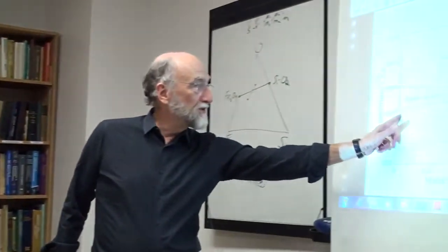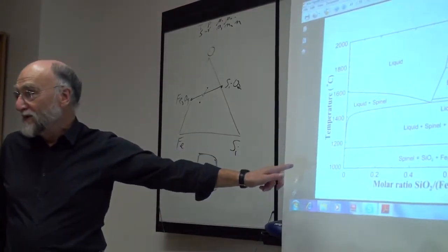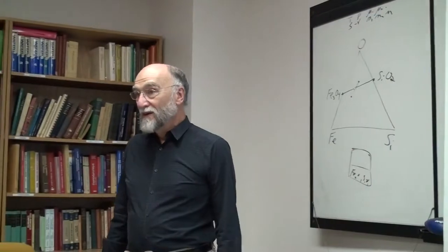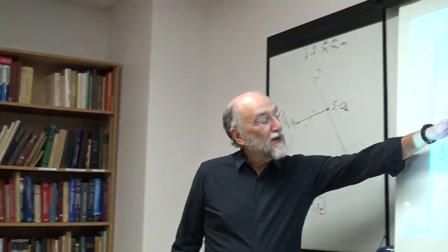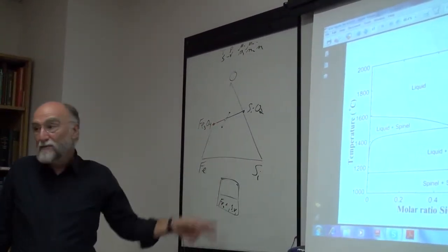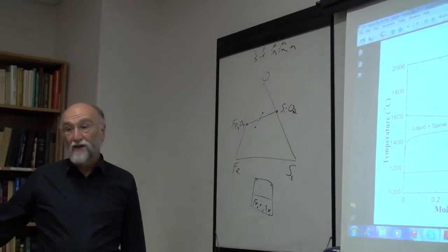You can see, for example, this is not what a binary phase diagram looks like. This is simply an isoplethal section across the system. In other systems you might find that it's fairly close to quasi-binary: most of the tie lines lie pretty close to that line, but not exactly, and there's no reason they have to.